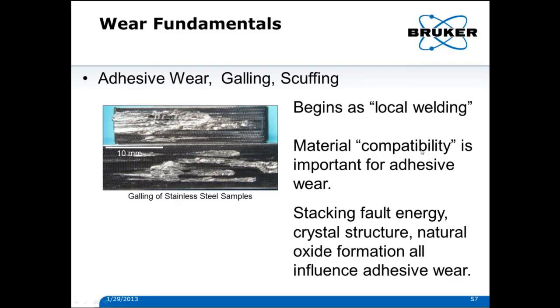So here material compatibility is important for adhesive wear. We really want incompatibility, so they don't have an affinity to bond or locally weld to one another. And that's all affected by stacking fault energy, crystal structure, natural oxide formation, all of these things.